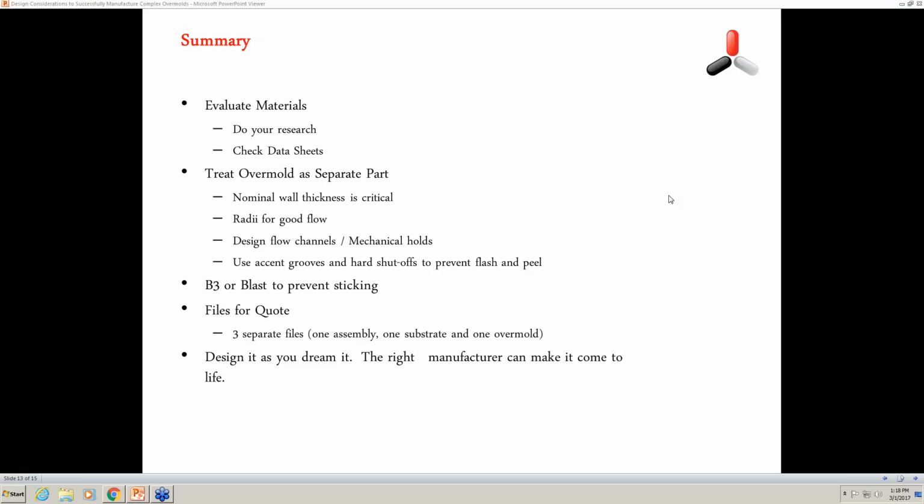Can you overmold clear PC and get optically clear results, both in finish and clarity in the lens? That's a really good question. I'm assuming just overmolding a clear window or a light pipe into another part. I have one project that comes to mind where we overmolded an actual clear window and a set of light pipes into a nylon part.